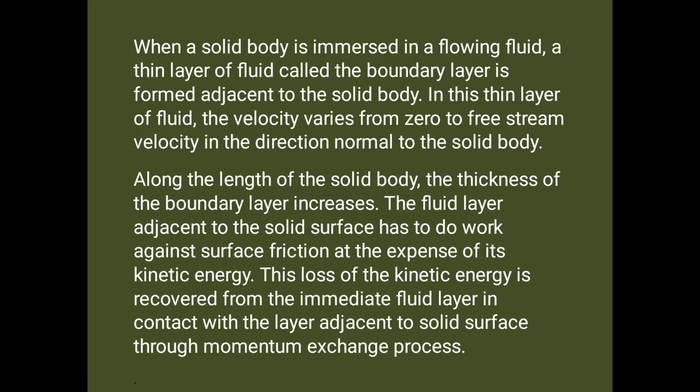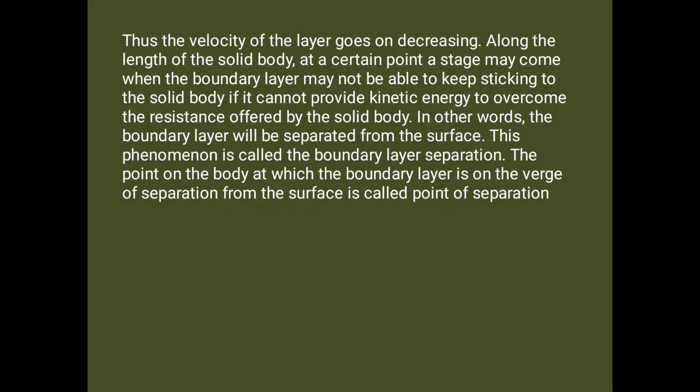The fluid layer adjacent to the solid surface has to do work against the surface friction at the expense of the kinetic energy. This loss of kinetic energy is recovered from the immediate fluid layer in contact with the layer adjacent to the solid surface through the momentum exchange process. Thus, the velocity of the layer goes on decreasing.